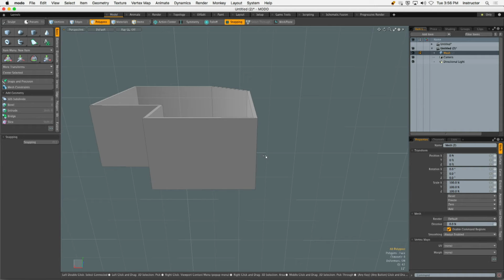We're trying to slice up our mesh. Not only are we trying to slice the outside of the walls, but we also need to slice the inside of the walls too, so we can create a hole, an opening, okay? What this is going to take us to is a really interesting tool set called Booleans, which will allow us to create geometry, right? And then use that geometry as a really fancy slicer, if you will. This Boolean operation is going to allow us to cut geometry with geometry, okay?